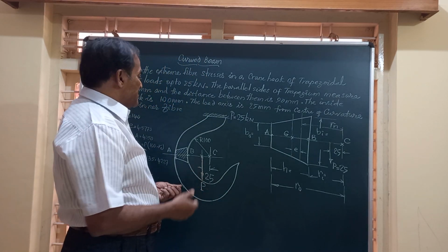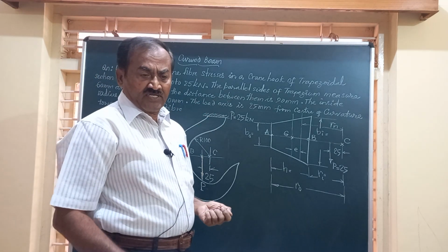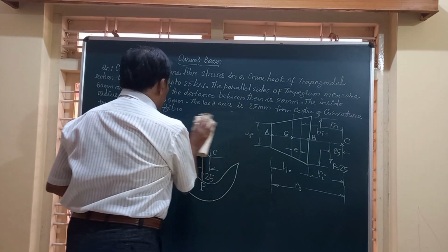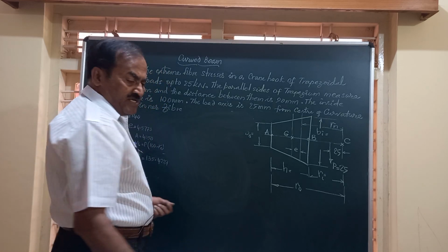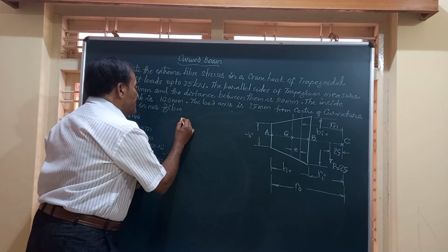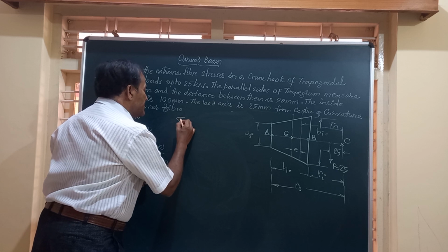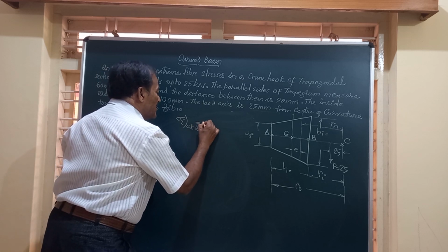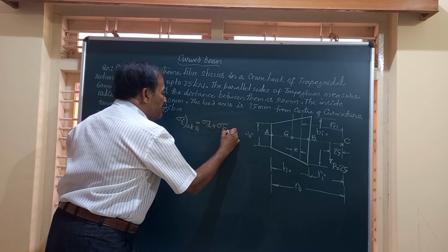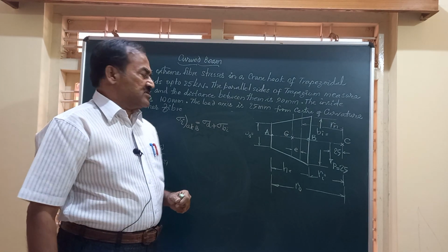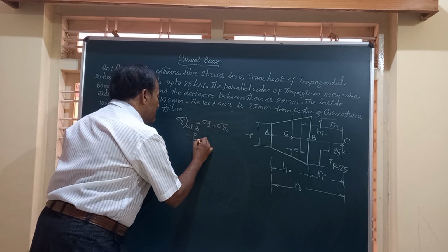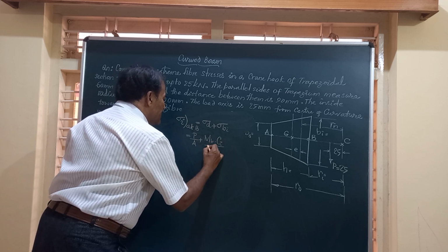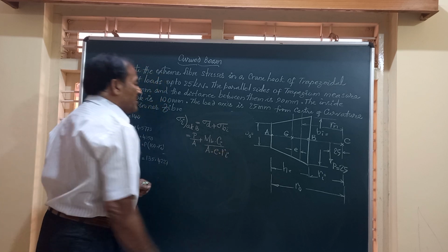Now friends, to find out the extreme fiber stresses, you have the fundamental equation given by the formula. I'll just remove this sketch and write down these values. So first of all, we will see how to compute the values of sigma i and sigma o. Friends, sigma i, the total stress at the point B, is given by the formula sigma d plus sigma bi. And remember friends, this is going to be a tensile stress. So sigma d is given by the formula P divided by area of cross section, plus sigma bi is MB into Ci divided by A into e into Ri. This is the formula we have got.